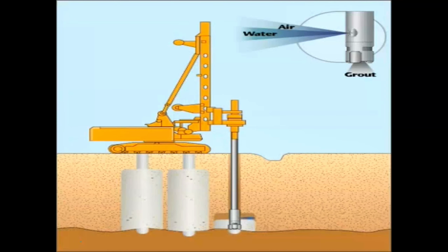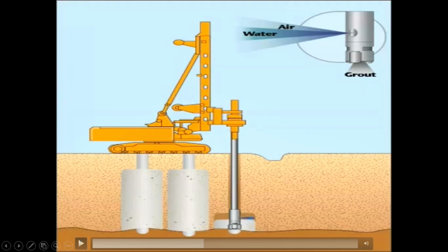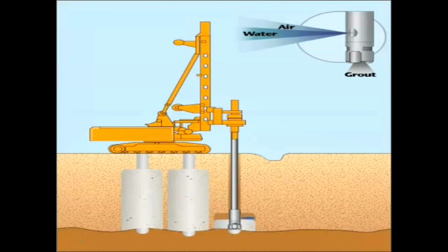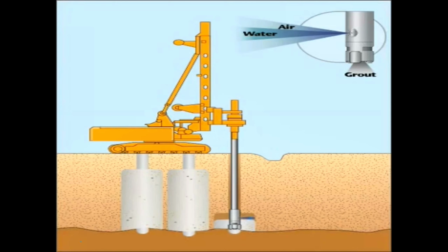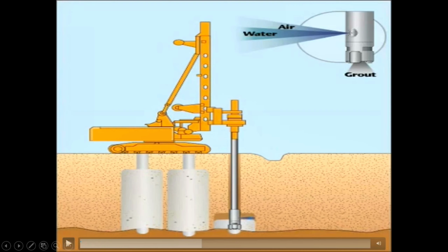Now, next, when I start the grouting, at that time I use air to remove the extra particles during the grouting process. Clear? So now if you watch that video, in the remaining process the grouting is going on, as well as the air pressure is removing those particles that can be accessible throughout the process. So now go with the video presentation.